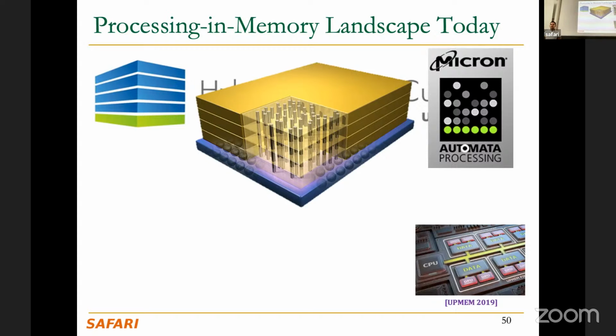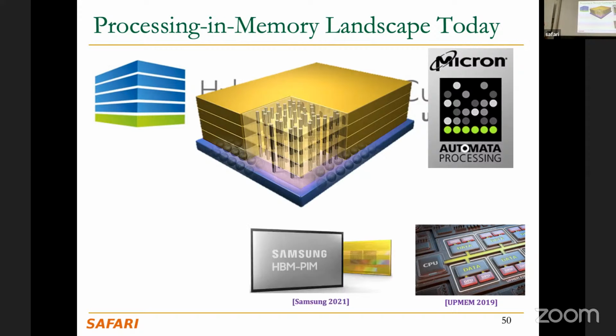Other startups are also looking into this landscape, this possibility of memory-centric architecture. We have this French company called UPMEM that created these DRAM DIMMs that are composed of both memory and some other cores in the same package, and they can do computation in the memory itself. Samsung announced in 2021, following this 3D stack organization, some processing-in-memory accelerators for neural network inference, particularly transformers. And recently, last year, they announced three or four more prototypes for the same system.